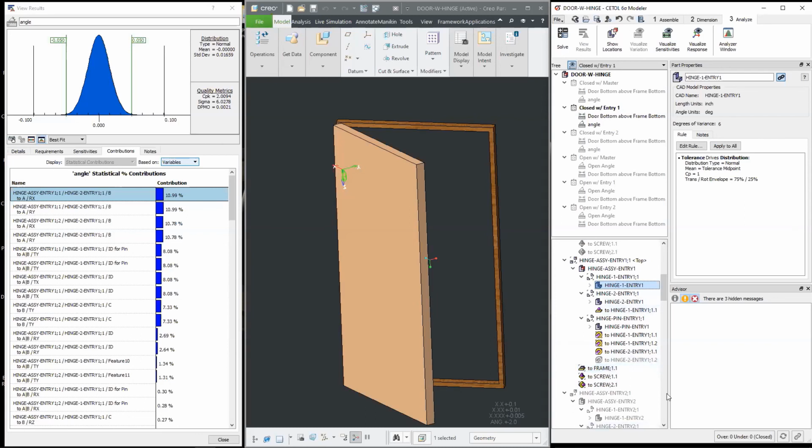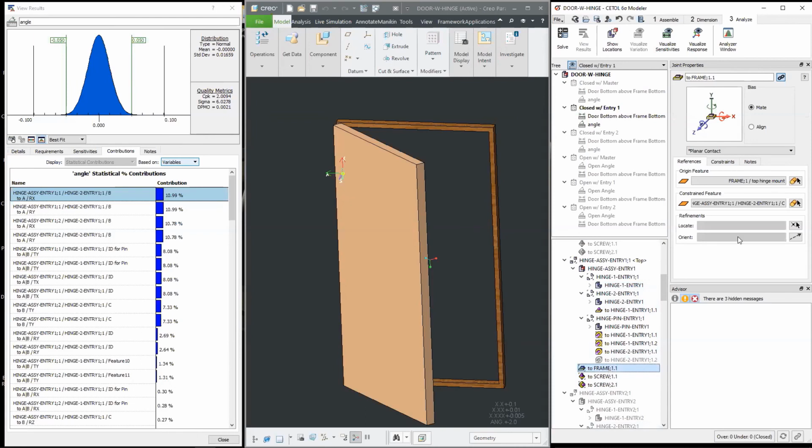Well, through that definition and the identification of primary, secondary, and tertiary joints, i.e. assembly constraints, it starts to drive you through the process of thinking about, okay, the features referenced by my primary joint are the best candidates to be primary features in the datum reference frame for their respective parts.